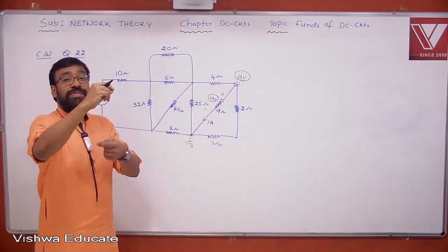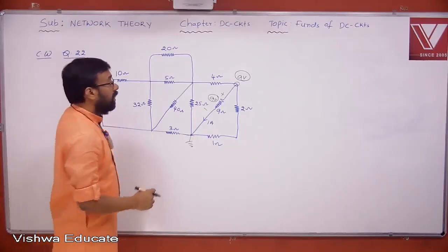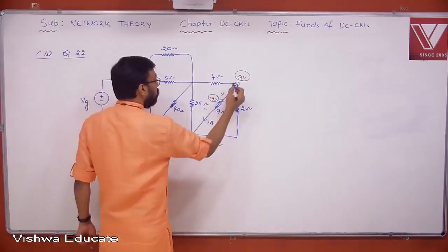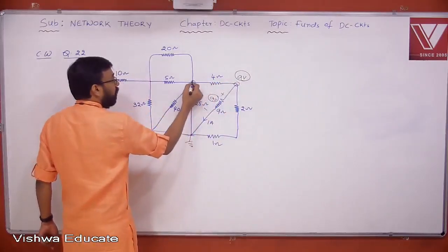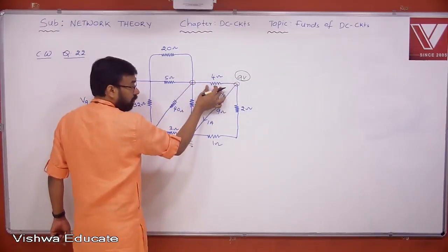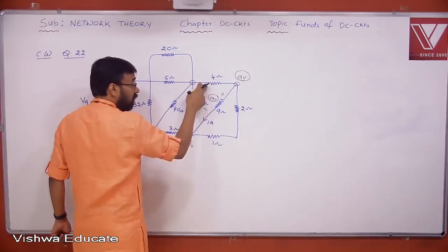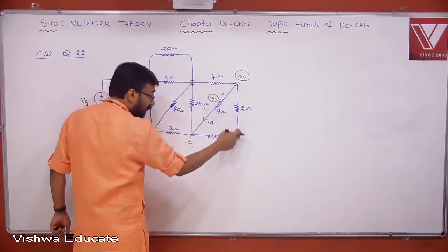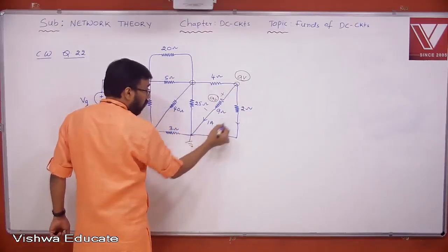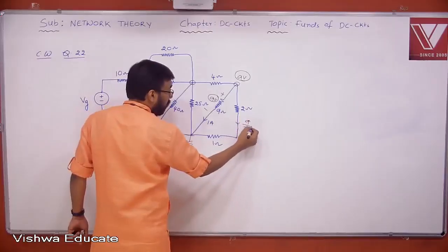Voltage must always be mentioned between 2 points. There is no single point voltage. Okay? So, this is a voltage with respect to this, how much? 9 volt. Let's jump from this point to this point. To jump from this point to this point, you need voltage. Yes or no? To find the voltage, you require current. To find the current, you require current here. Therefore, what is this? 9 minus 0 by path resistance. 9 by 3 ampere.